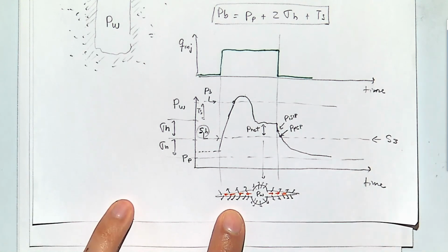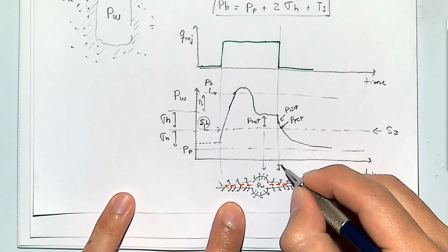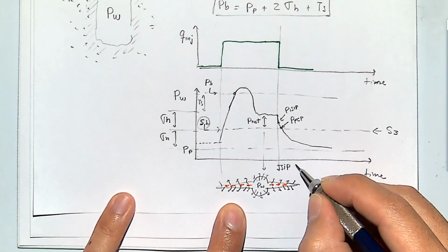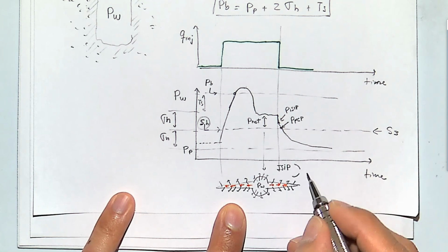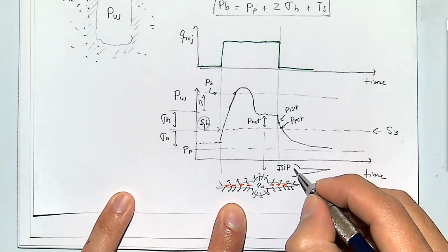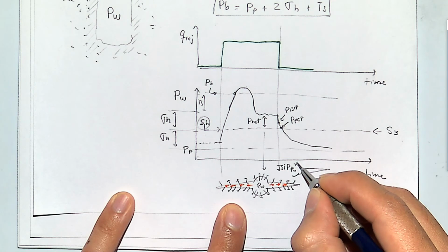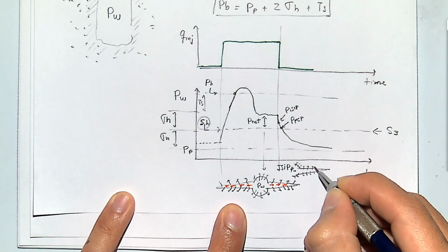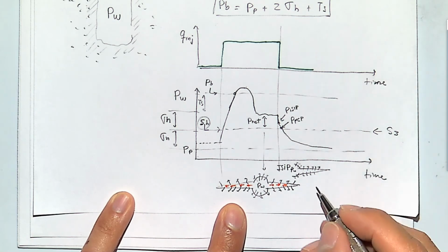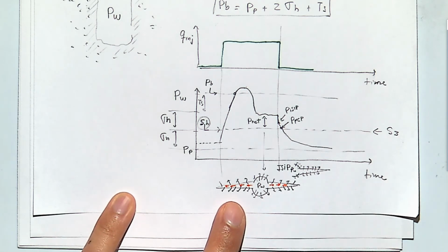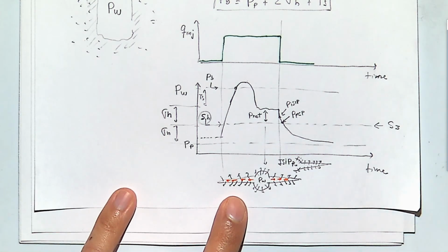let me make two schematics here. One for instantaneous shut-in pressure. I'm just going to make half a wellbore. When you shut in the wellbore, you have leak off from the fracture and from the wellbore, but there is no more flow into the fracture because you're not injecting anything. That's at the point at which you shut in the pumps.